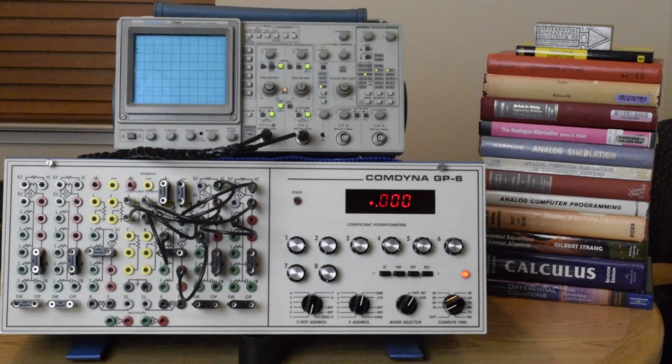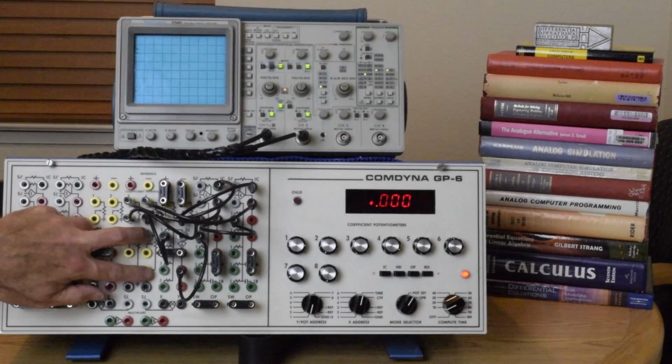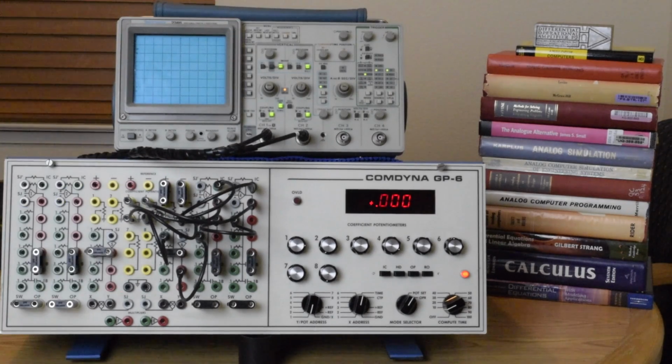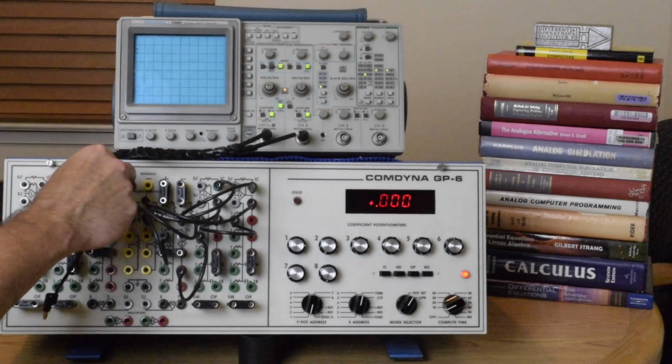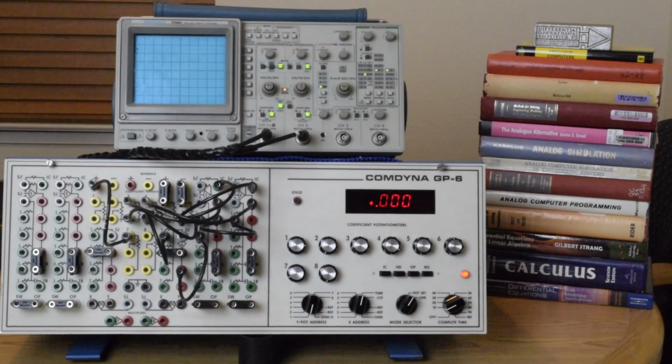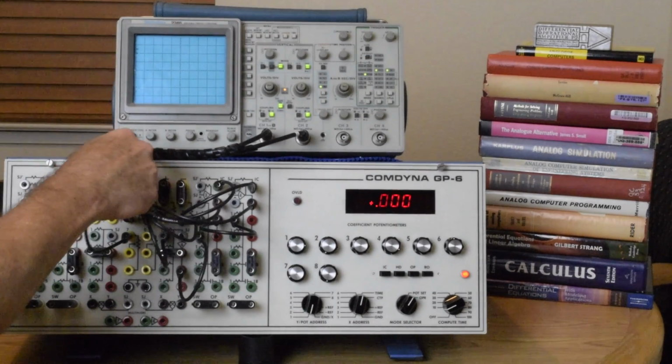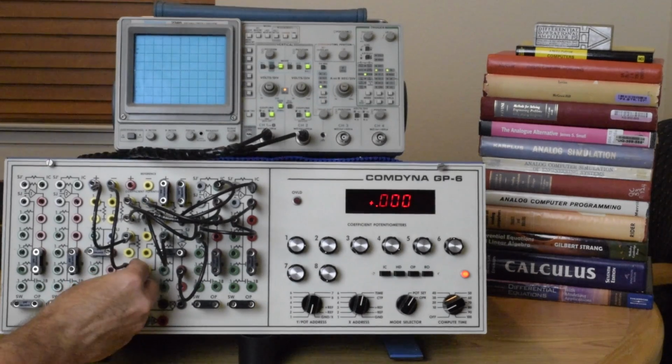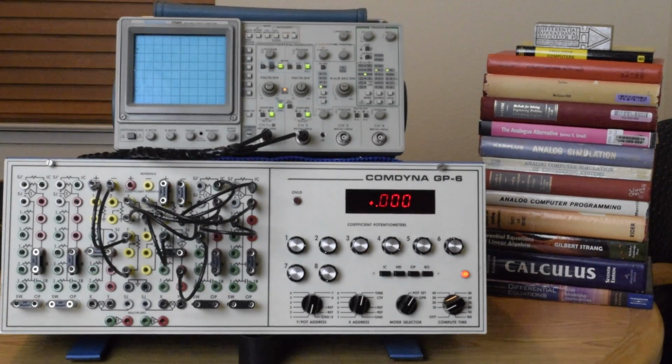But for the demonstration I'll do in this video, I'll actually use the dual-ended potentiometers so we can more easily see what happens when you vary these voltages through the entire range of the analog computer. So I'll go ahead and set up the potentiometers right now, and it's just done with these jumper wires. I'll go from the positive reference to the upper leg of potentiometer 7, and then from the negative reference to the lower legs. So the references are actually plus and minus 10 volts, so the output of that potentiometer will be able to vary all the way from minus 10 to plus 10.